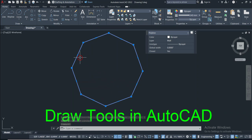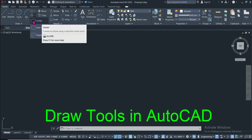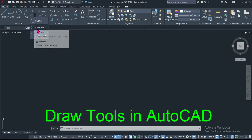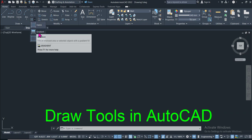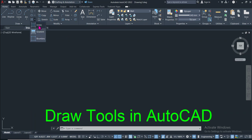So the next option available in the draw tools is the ellipse, and when you click on the drop down button, there are 3 options to draw the ellipse. First is the center, then the axis and end, and the third is the elliptical arc. So you can draw these 3 things depending on the available data. And the next option that is available in the draw tool is the hatch. In the hatch there are 3 main options: the hatch, gradient and boundary. So depending on the requirements, you can select this or this or this option.